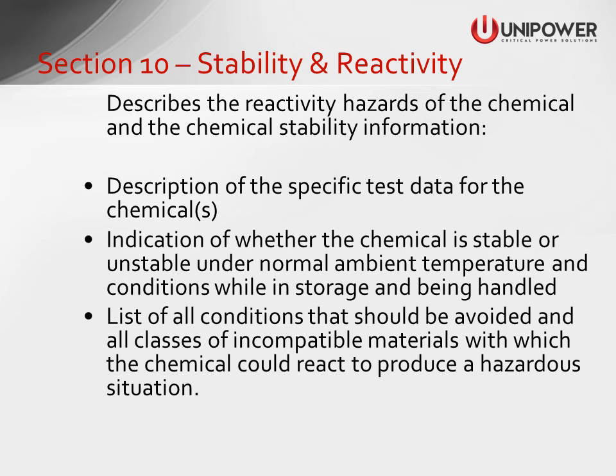Section 10 speaks about stability and reactivity of the chemical. This section describes the reactivity hazards of the chemical and the chemical stability information, which includes the description of the test data for the chemical, indication of whether the chemical is stable or unstable under normal ambient temperature and conditions while in storage and being handled, and a list of all conditions that should be avoided and all classes of incompatible materials with which the chemical could react to produce a hazardous situation.